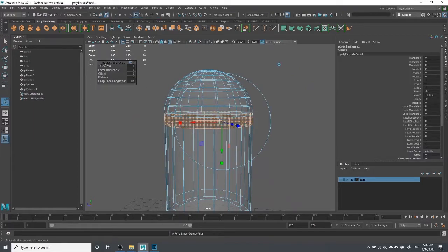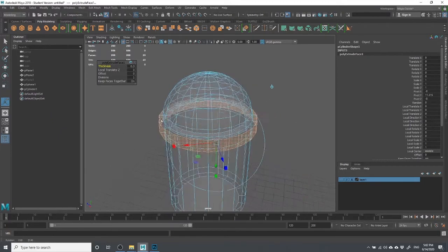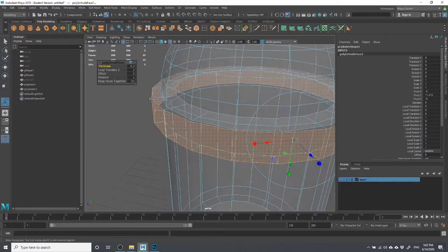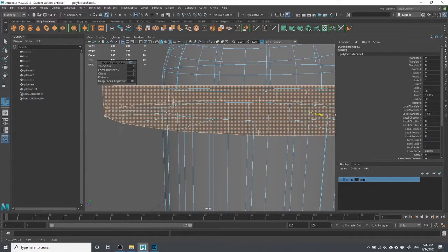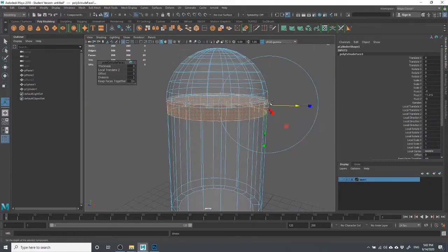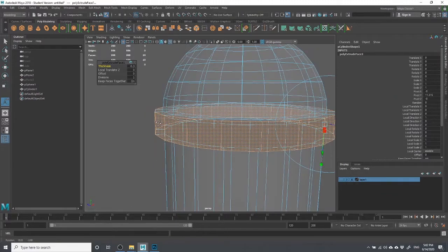This menu comes up here, and what I like to do here is just work with the thickness. The thickness will give you sort of a straight extrusion without it growing in the normal direction. So if I do this, this looks pretty good too, but depending on the shape that you have, this might grow in the direction of the normal, or let me say the direction of the facing of the polygon.